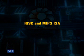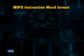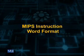However, let us talk about the MIPS instruction word format. For this purpose, we can say that the MIPS instruction word is designed such that it has three different types of formats. The register type of format, normally written as R type format. Second is the immediate address format, usually written as I type format. And the third one is the jump format, usually written as J format. So let us consider first of all this R type format. For this purpose, have a look at this.